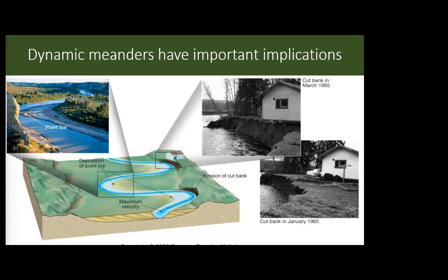However, if you build on a depositional bar, you're probably a little more safe. You're not going to have to worry about erosion at those points. You're going to have nothing but deposition. You may actually have a problem with deposition at some point, which is an interesting problem to have.